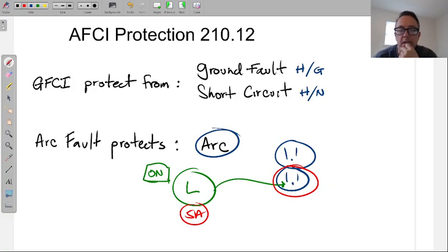That's what the arc fault protection outlets are for, or devices which become outlets. So these days, if you've ever seen them, it's a little door, a little flap on the neutral and the hot. As soon as you pull the plug out, they close. Any arcing that happens stays inside. What they don't want is arcing on the outside. And again, remember, the code book is regulated by the fire department. So I'm guessing the fire department has determined that the arcing from people unplugging from outlets has caused enough fires that they're like, hey, we need some special outlets now.